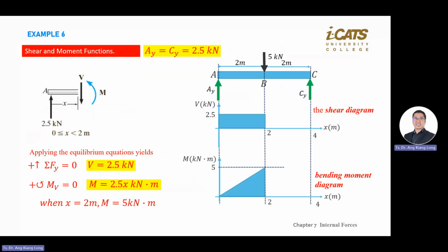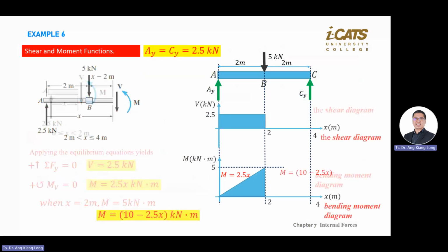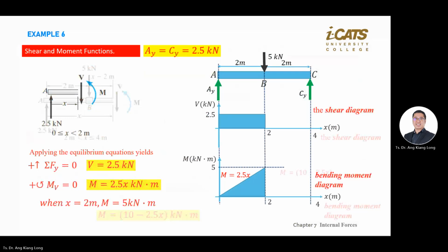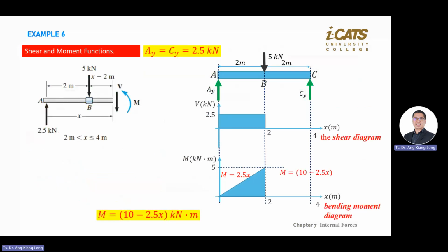Okay, repeat the same for the other section. It's important you write the equation on the line in the moment diagram, like in this case, m equal to 2.5x, this line. We have done the first section.